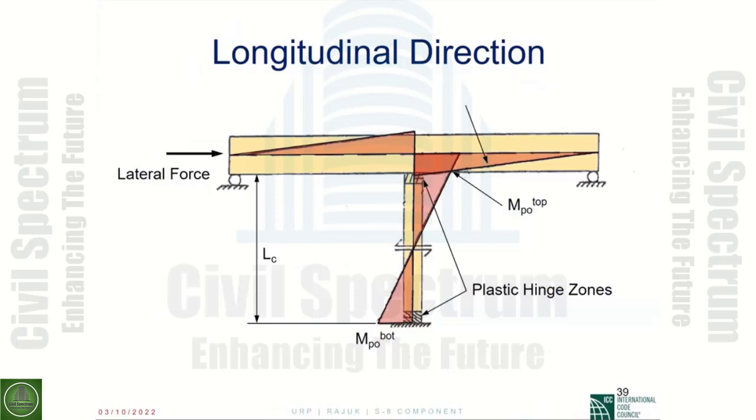Based on this mechanism, you will have seismic forces at the end of the bridge where the bearing is, and one of them will be a compression force, and the second one will be a tension force. So that will be an uplift, and if the bridge is not heavy enough, it will uplift.